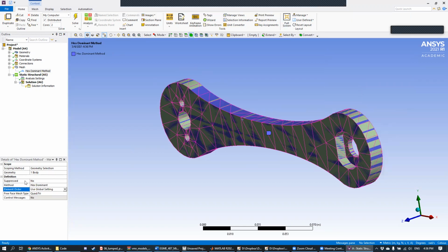All right. The other setting that we're going to set here is the element order. We actually talked about this briefly earlier this week. Remember when we were solving for the solution to the weak form of our boundary value problem, we had to assume a form of the solution. For that particular example, we assumed a quadratic function.